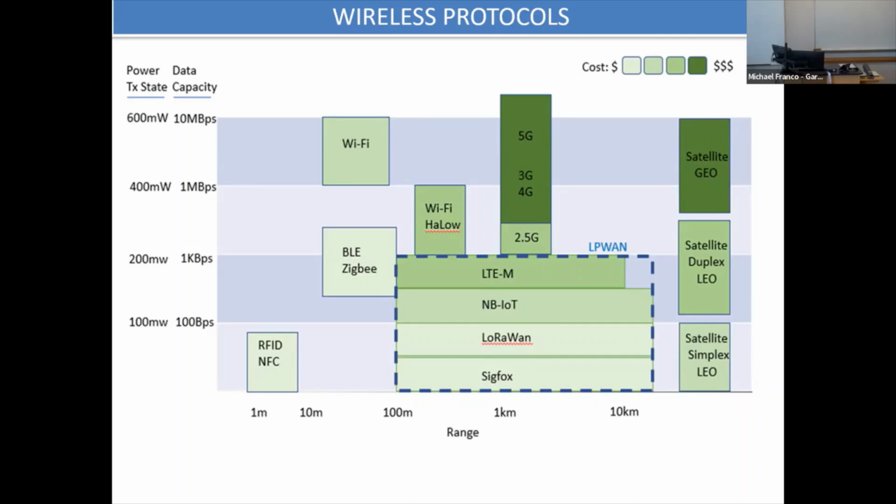NB-IoT is interesting because I don't have to buy my own gateway, because any 4G and 5G base station supports LTE-M and NB-IoT. The commercial implementations I've been involved with that have gone over 20,000 units pick LTE-M because it's reasonably fast and it's got widespread coverage through North America. And it's low cost, low speed. It gives you over twice the distance of normal 5G because it's slower. NB-IoT has over 4 times the distance and it's even lower power yet.